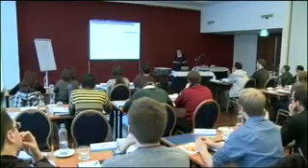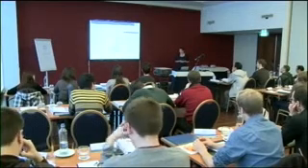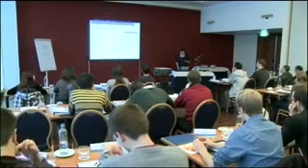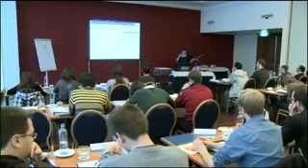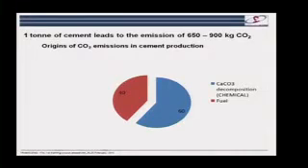So intrinsically, it's a very low energy and low CO2 material, but because we have these enormous volumes produced, this means that cement production worldwide accounts for about 5 to 8% of man-made CO2 emissions. And this is where the pressure comes really to continue to improve this. Now, in understanding how we can go about improving this, we need to know particularly what's the origin of those CO2 emissions. So on this chart here, we see the origin of this CO2 broken down into two parts.